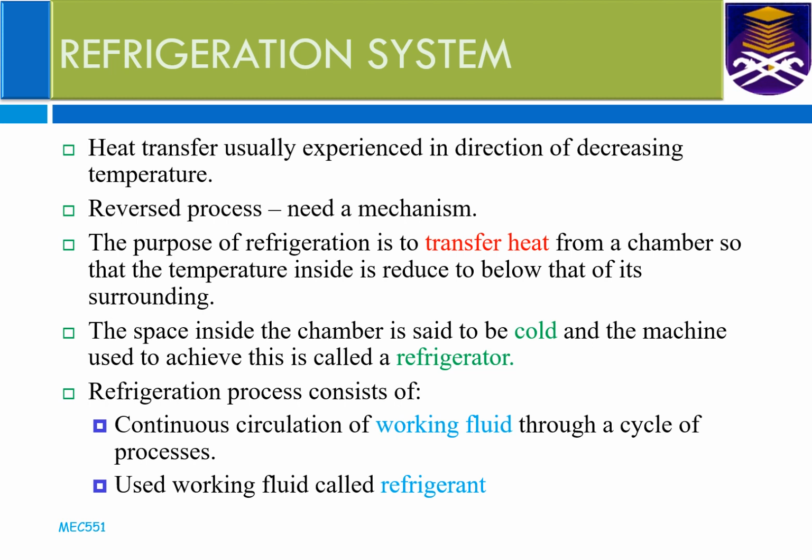For example, if heat is taken from the refrigerated space, which is the desired output for the cooling process, it is called the refrigeration cycle or refrigerator. But if it is the other way around, if the requirement is to heat up the chamber or space, then it is called a heat pump.